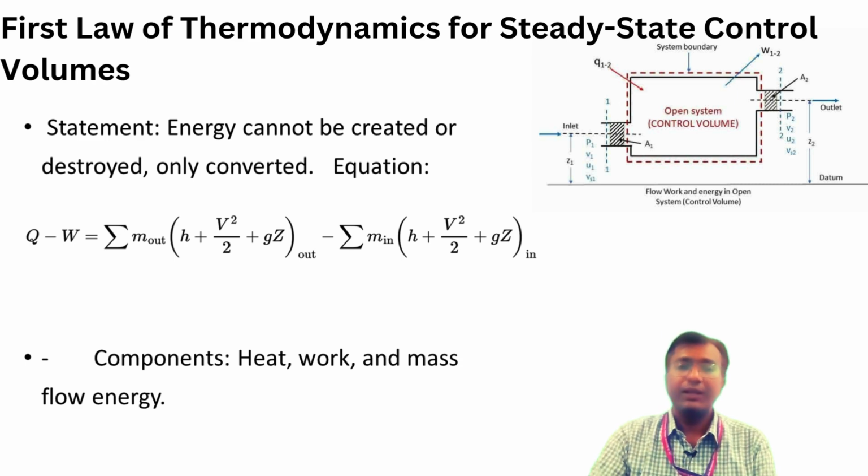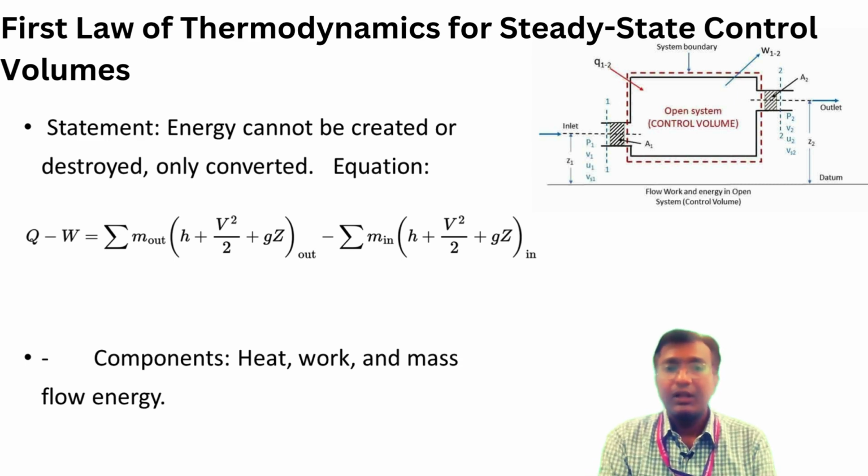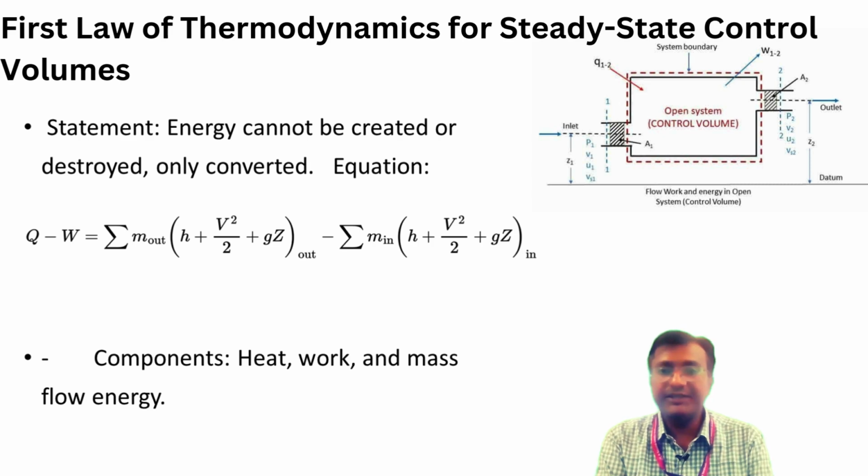Now here, the steam which enters the turbine has a very high enthalpy. And what is enthalpy? It is nothing but the summation of internal energy plus flow energy. It does work on the blades and exits at a lower enthalpy. Now, this equation above quantifies the work output.